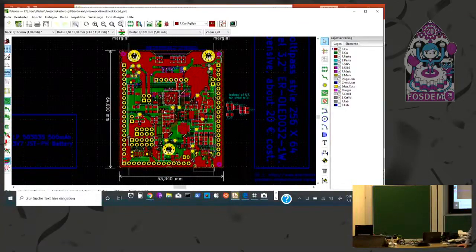So what we need to do is, from power on, loading in authenticated SPL code, bootloader, kernel, file system, right the way through. Now, it would seem sensible to use this secure element, the root of trust, to underwrite all of that, but we don't seem to be able to.